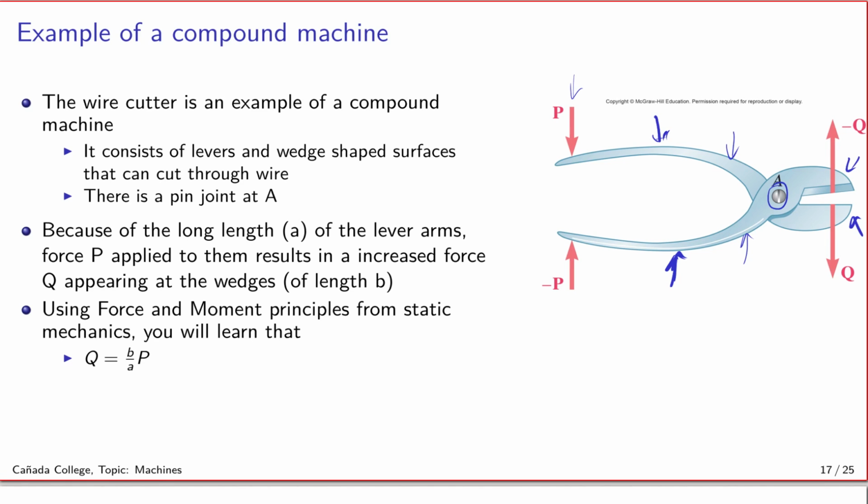And you will see that as you try this experiment and you move slowly to further and further away from the pivot point till such time that you reach the position P. So let's call this distance A here, right? And let's call this distance B here. Okay? If you actually apply the force at P so that you use the full length A, you will find that it's much easier to break or cut the wire than if you applied the force at some position here, much closer to the pivot point.